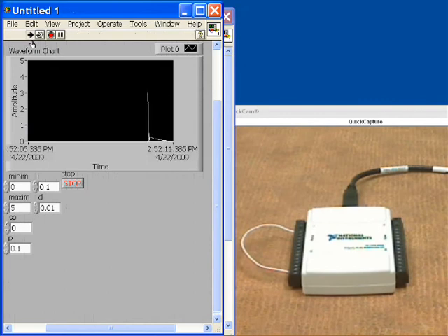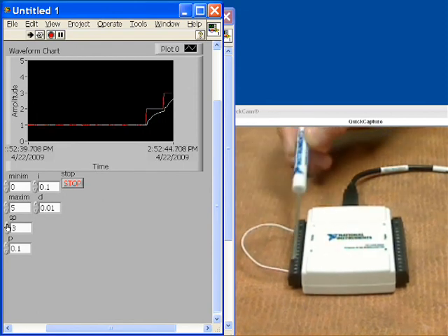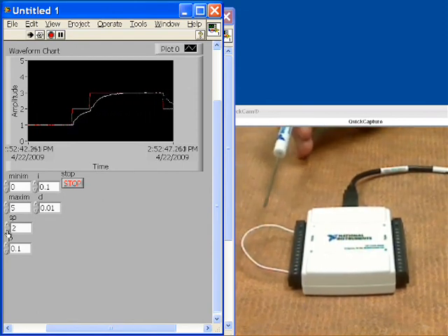When we go ahead and run this, we'll actually see that white line being the analog output, and then the red line, which you can see there for a little bit, that's going to be my set point. So if we begin to change this, you'll now see the red value, which is the set point that I'm controlling. It's changing, and the system is then responding through the control algorithm to try to match that red value. At this point, it's pretty responsive. If I was sending this out into the real world, I would expect my system to be in between this loop right here and be responding to the stimulus from the analog output into the analog input.